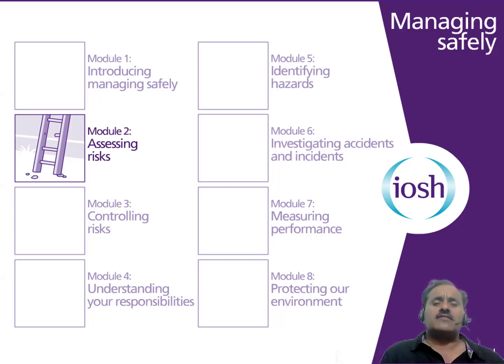We have reduced the hazard, but still we came to know that there is residual risk. If the residual risk is again more than your limit, like 85 decibel, then we will also provide the personal protective equipment to the workers. So my dear learners, the third level of the risk assessment is controlling the risk. Risk would be controlled in an efficient manner, so that the purpose of carrying out the risk assessment, again, to identify the problems, to assess the problem, to remove the problem.